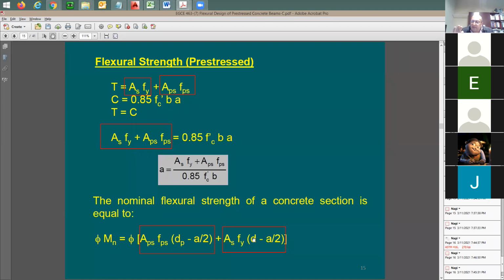Alright. These are not the only 3 cases that you may see. There's another case in which you're going to put the formwork, put the reinforcing bars, all right? Cast the concrete. And then apply some of this post tension. It's going to be partially pre-stressed, enough to support the beam weight, and then strip the form. You just take the forms away, right? Now the beam is going to be able to support its own weight with the help of these conventional rebars and the partial pre-stress. And then you leave it for some time because you're still in construction. You don't really need the full pre-stress.